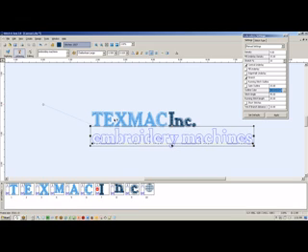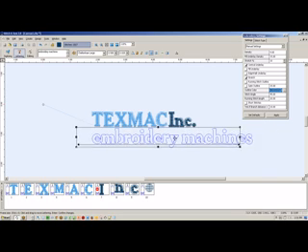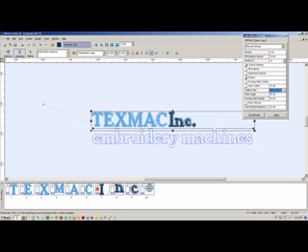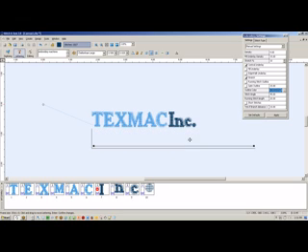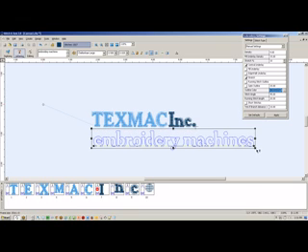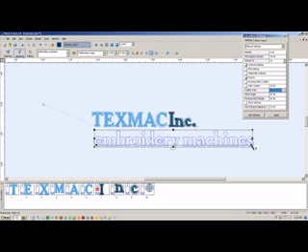So you can still move stuff in lettering mode. Just move your cursor right over the middle of this and drag that. I'm going to line it up to one side of the text, and then if you grab a corner node where it's a square and you drag, when you resize, it should keep it in proportion.